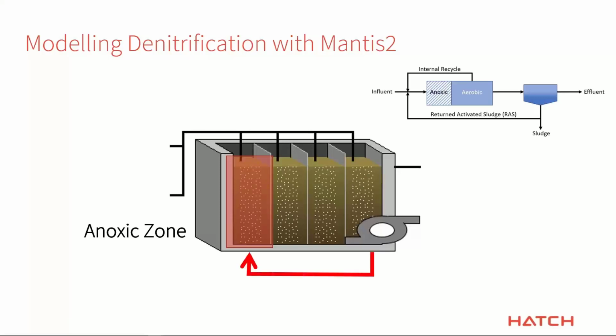And then the second thing you can do is put an internal recycle. So on your GPSX drawing board, you won't actually see the internal recycle. It's actually just there inside the object. But I find this way is a little easier to manage, especially if you have a very complex or detailed plant and you've got lots of objects and flows moving around on your drawing board. Sort of tidying it all up and moving it inside one object can be very helpful.